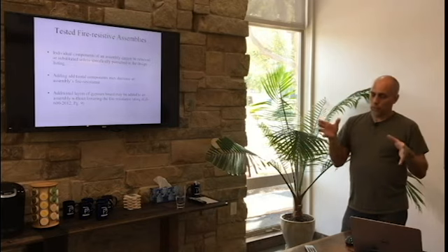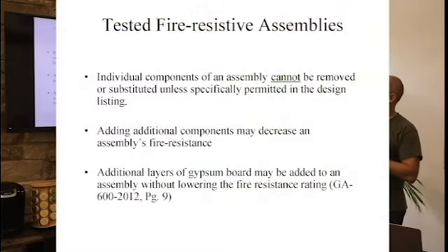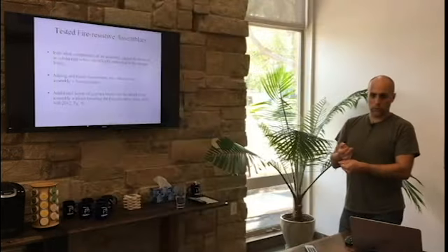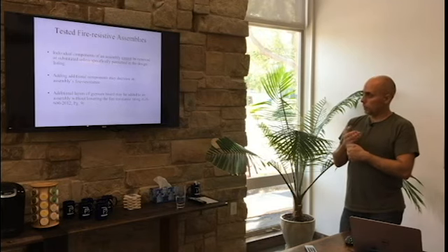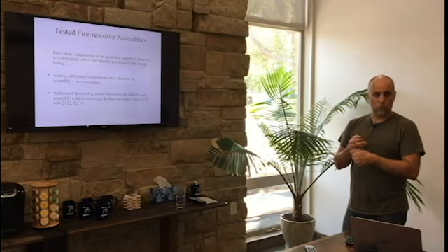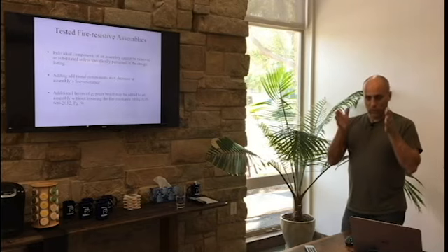So the key component to those fire resistive assemblies, you cannot remove nor substitute and must use all of the components as listed. No ifs, ands, or buts. If it says optional, okay, don't have to use it. If it tells you you must use this particular gypsum board, you must use that particular gypsum board. You cannot in any way substitute unless it allows substitutions or various alternates, because that's what they tested it with.